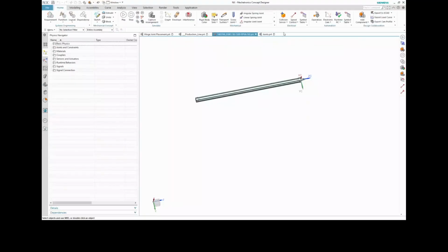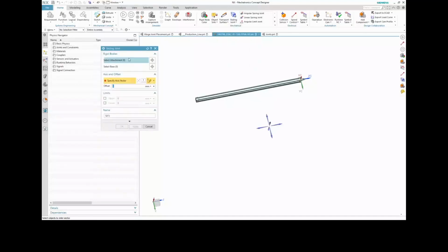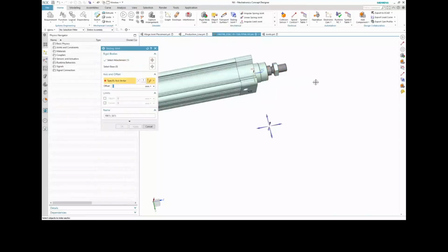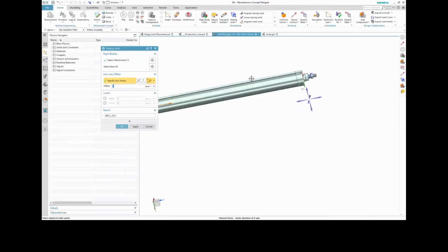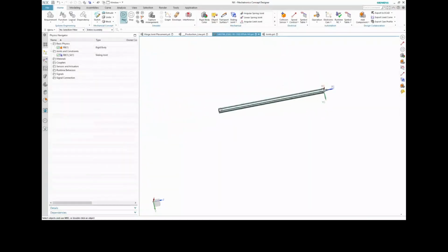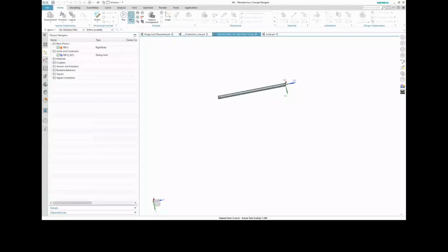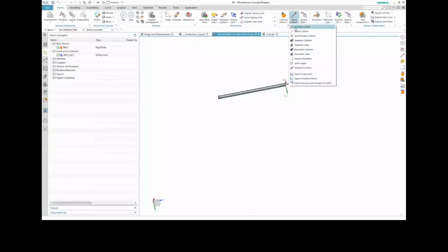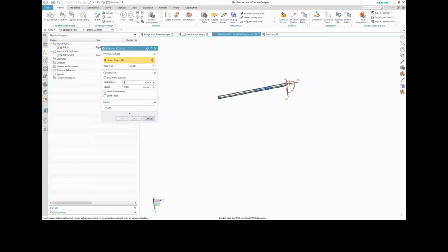So when I play this, you would see it falls down. It fell down because if you notice the Z direction is there, so the gravity works in the negative Z direction. So it falls down like that. We can now apply some position control to this. So we have a position control. I select my joint and I can say destination 0 and speed 1500, and I can write to this destination when I start writing my operations. When I say okay, now it doesn't move because it's now controlled by my position control.